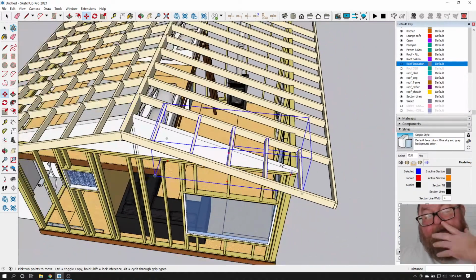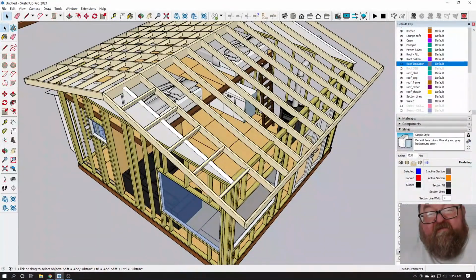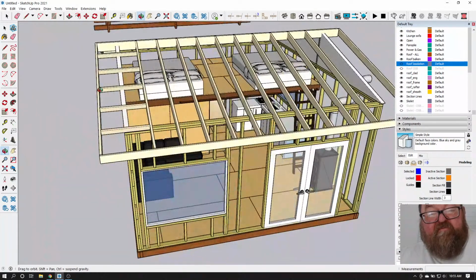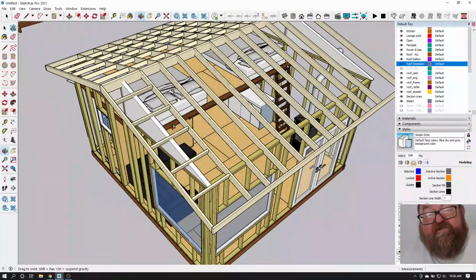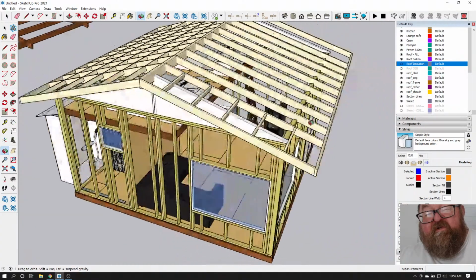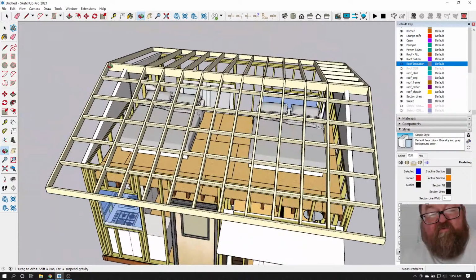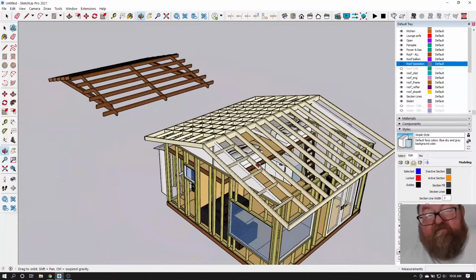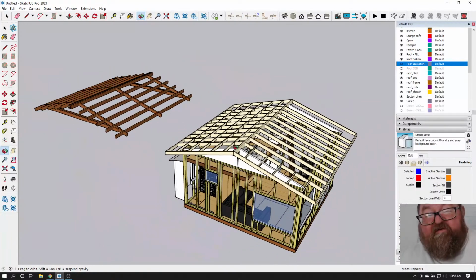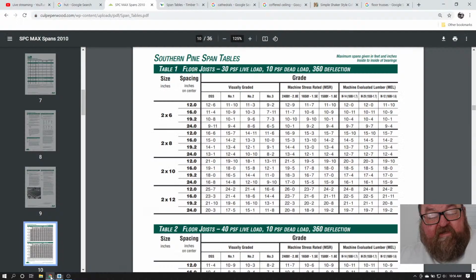Okay, see? You still have to have those because that's what's going to support your barge rafter, your overhang out here. My idea was just to continue that spacing, whatever it is. If you want this coffered look, just continue it across like this. Then you would have support for your barge rafter at each end. Anyway, I gotta move on to another project, and this was a freebie, so I can't spend too much time on it.